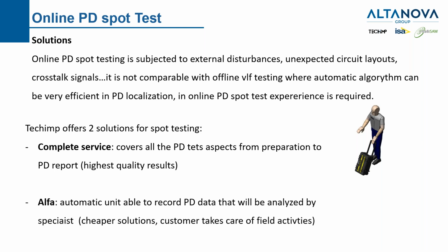Another solution, cheaper, is that the customer may want to test the cable without having the service team going to the site. So they can require an Alpha instrument, the one I explained in the beginning, that is slightly automatic, to make a record of the PD data.